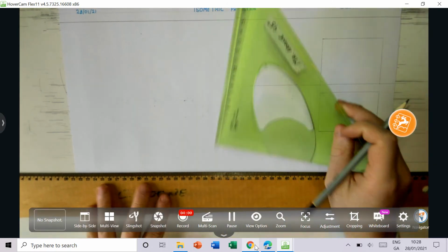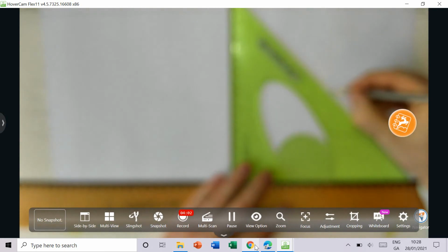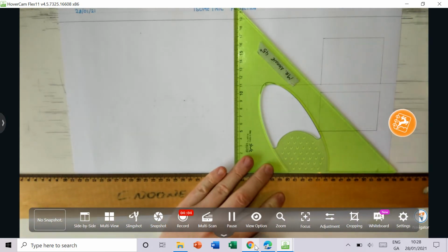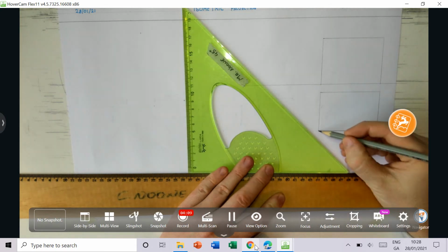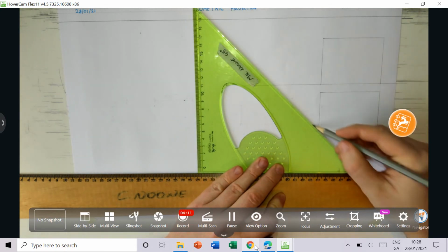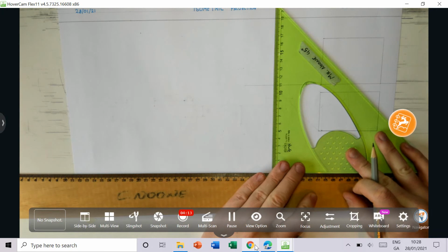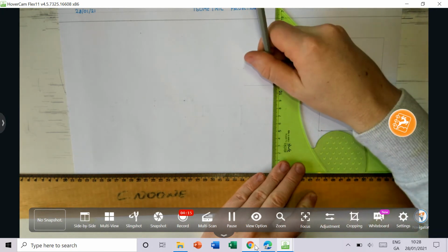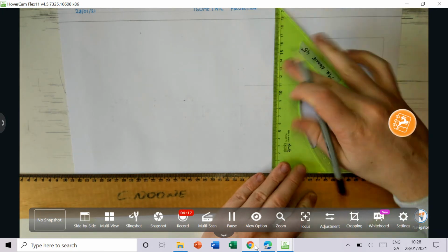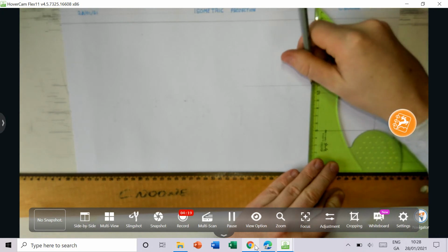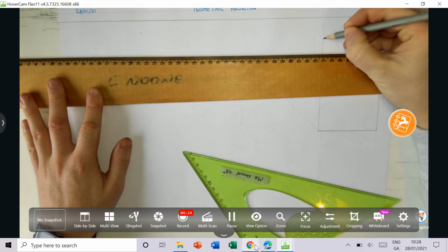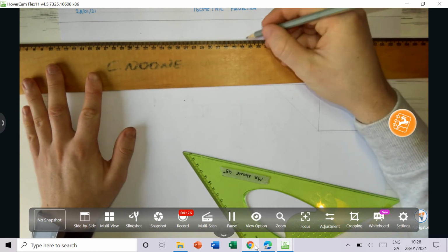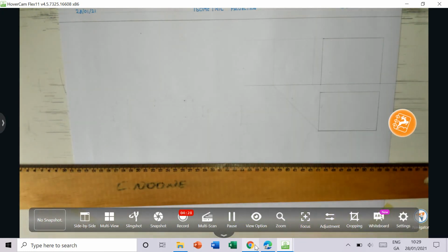Okay, our plan is going to fit in there, and to get where our end view is going to fit, we can project up 2 lines here at 45 degrees, project them vertically up, and our end view is going to fit into this rectangle here as well.